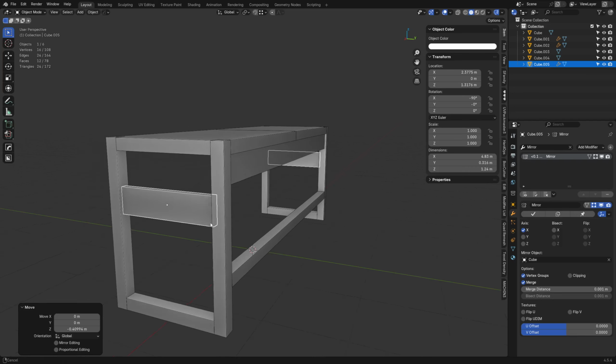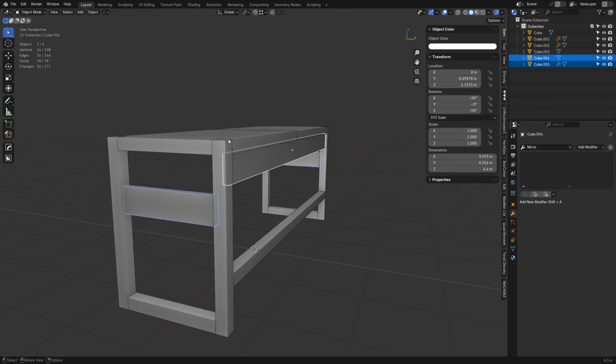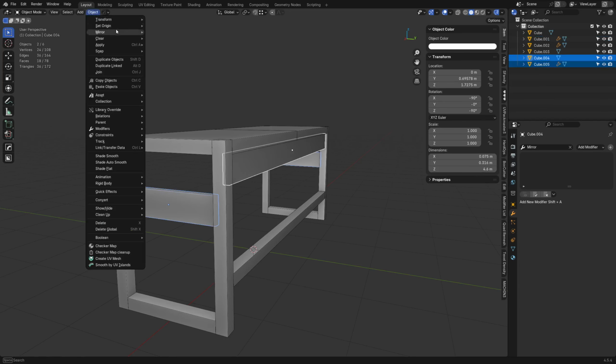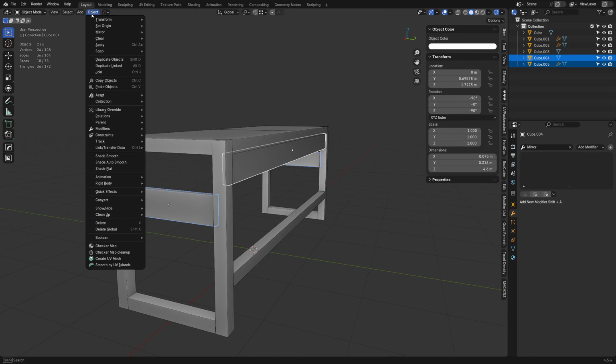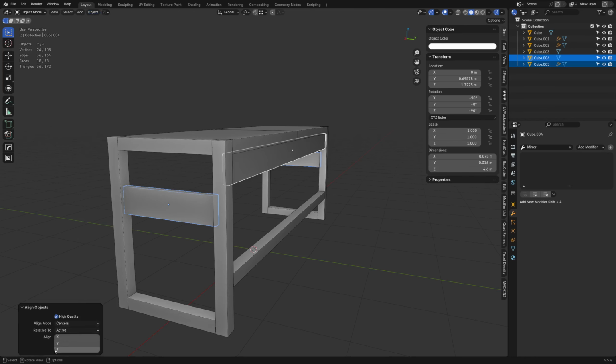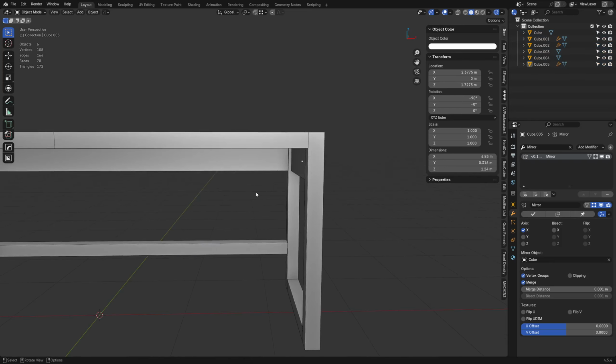Another thing you could try maybe is if you select this object, shift select this object, you can do transform, align. Oh, maybe it's not transform. Try this again. And no, it should be over there. Yeah, align objects is right there. Okay, so grab this one, shift select this one, transform, align objects. You'll see here, nothing is selected right now, but you can align on, say, Z, right, or Y or X. And we can also hold shift and select multiples if we need it. That's another option. But in our case, it was Z. And you can see they're back together the way they should be. So that's good. We got this all going like this anyways.